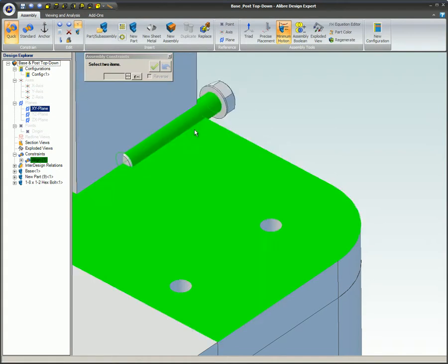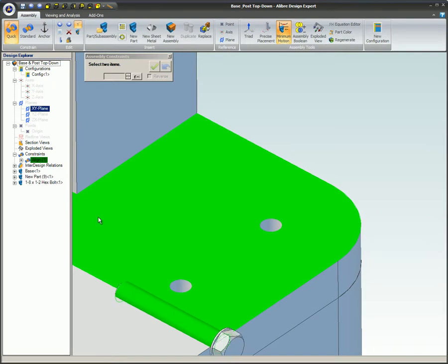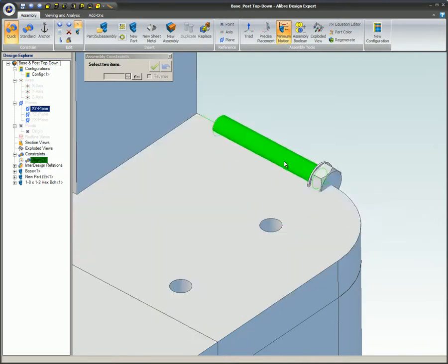While dragging the part, hover the mouse over another part. When the mouse hovers over an area of another part, the area it is over will also turn green. When this happens, a constraint will automatically be previewed. In this case, an align constraint is applied which makes the axis of the cylinder and the face of the other part parallel. Continue dragging the first part around the second part.